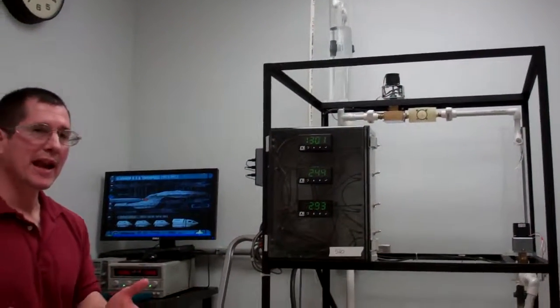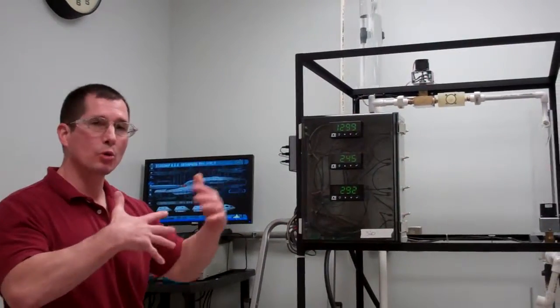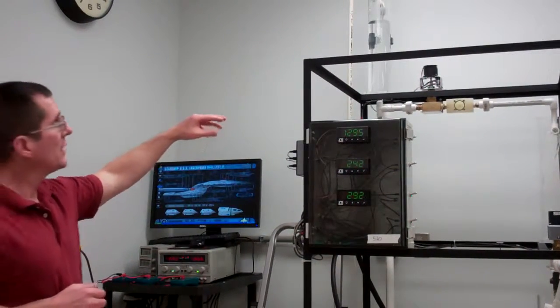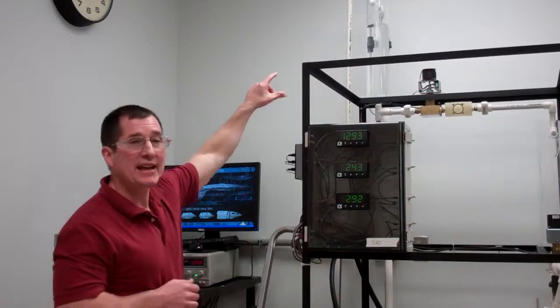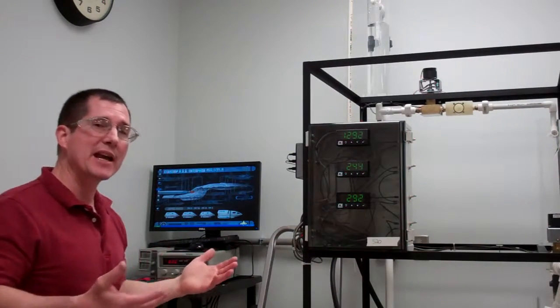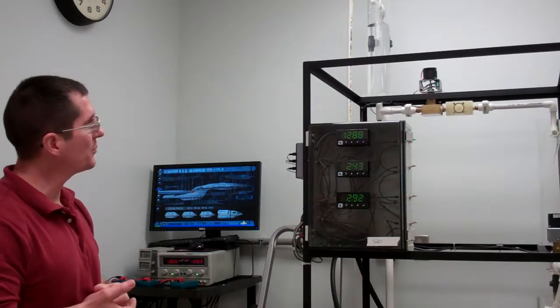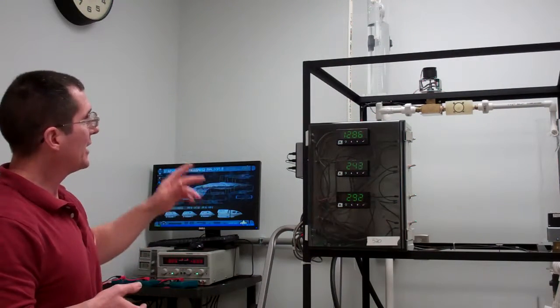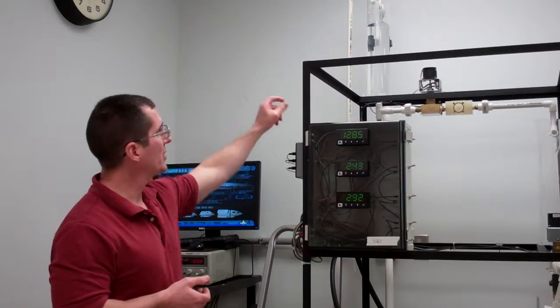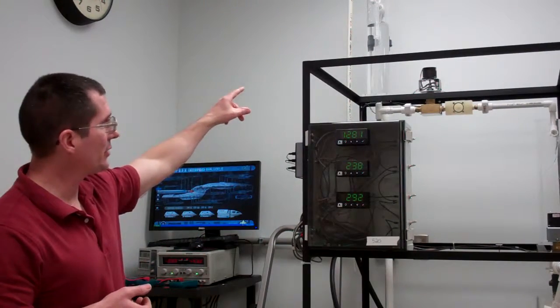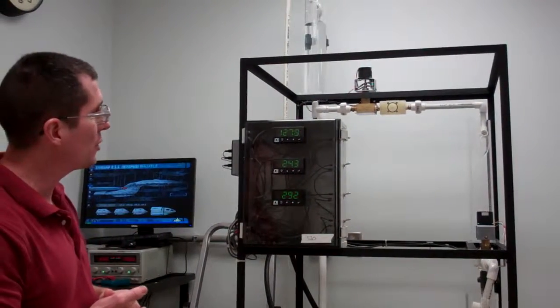Now, one thing that we have to know is, what is our control range for our valve? Because we may be able to get more flow through the valve if, say, the level of water in the tank is higher than when it's lower. And so that's kind of the range of control. We want to look at the different ranges of control that we have for our valve. That's something you're going to explore in the first lab. Not only are you going to characterize valve 1 for tank 1, but once you characterize that one first, then you're going to characterize valve 2, and you're going to compare the two. That'll be one thing that's important for your report.